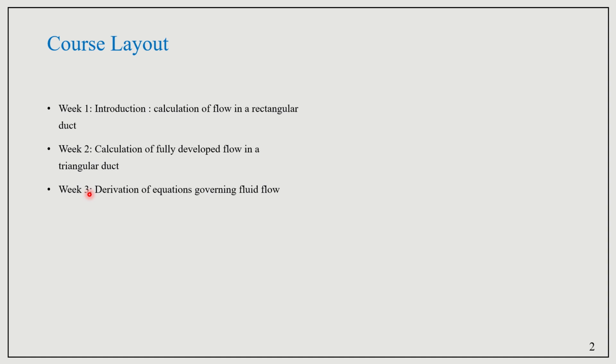So CFD is nothing but wherein you solve the problem at hand. So how do we go about solving the problem? We are just solving the equations, which define the fluid flow. For example, if there is only cold flow in the system, that is, there is no exchange of heat or exchange of mass, in the sense that there is no reaction happening inside the system, we have only the continuity equation and momentum conservation equations in the XYZ directions.